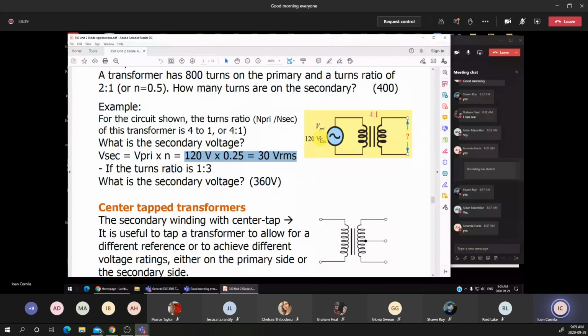Again, the input voltage can be given in RMS, peak, average, or peak to peak. Make sure that you do the conversion: find the secondary voltage, and after that, convert to the peak. Remember that all the quantities for AC theory are related to the peak voltage: peak, peak to peak, average, and RMS. Now, the question is, for a full wave rectifier, I'm using 2 diodes and a center tap transformer.